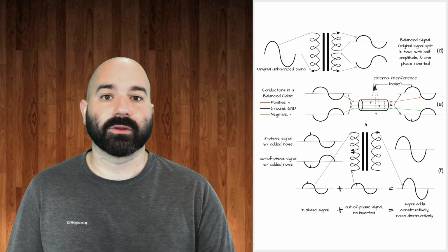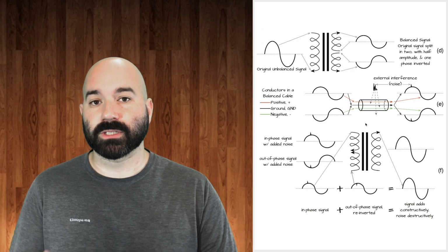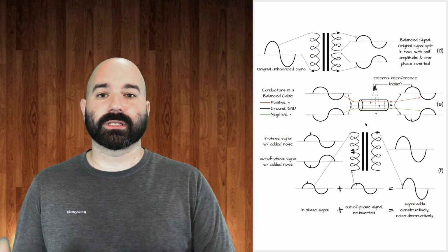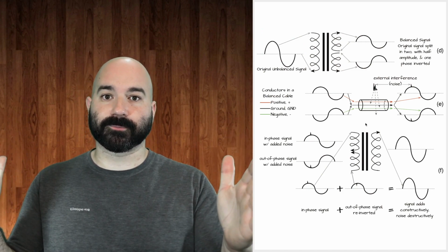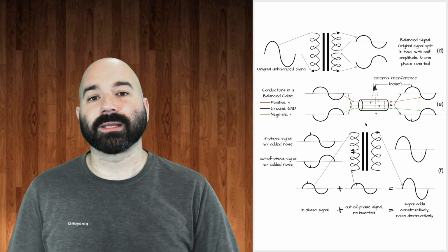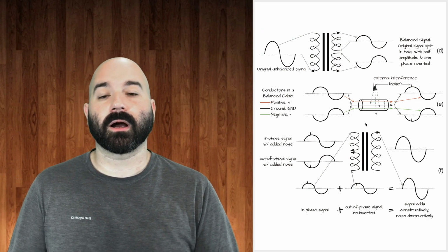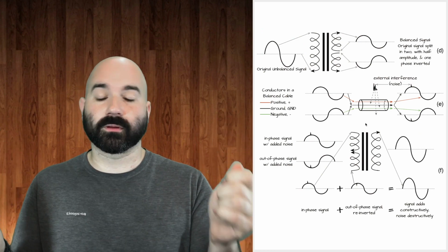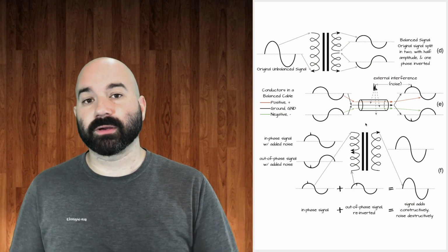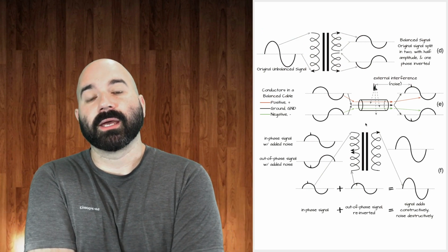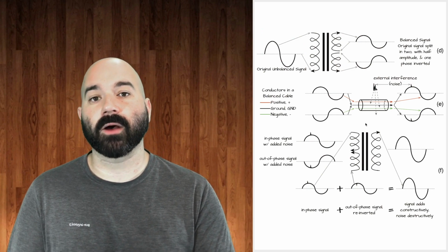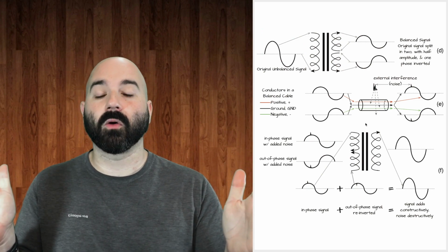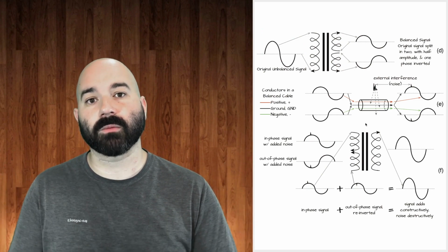So how do you fix the ground loop? Well, you can use a DI, or there's other buttons on different devices, but essentially you just disconnect the ground from one device to the other, not necessarily disconnecting the ground within the cable itself. Now, disconnecting the ground from one device to another so that we get rid of the ground loop is a very easy thing. Most DI boxes have a lift switch on it, and it's a ground lift switch. And essentially, you can choose to connect the ground between the two systems or lift the ground so you do not have the ground loop problem.